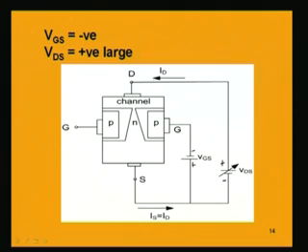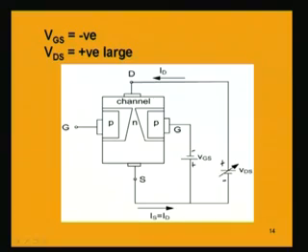Initially when we have a smaller drain to source voltage, the current will be increasing along with the increase of drain to source voltage, almost as in a linear region, because it is like an ohmic device now. The n channel resistance will be defining the current, and when VDS is small, an increase of VDS will give more force on the electrons in the n channel, so current will increase.